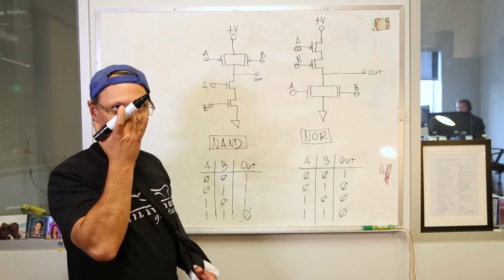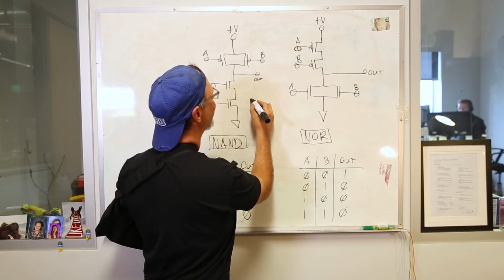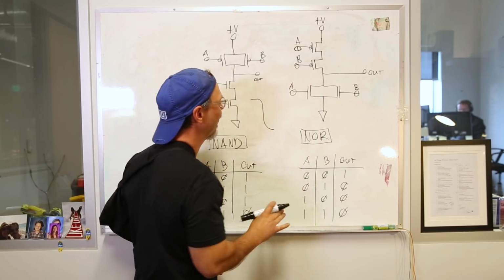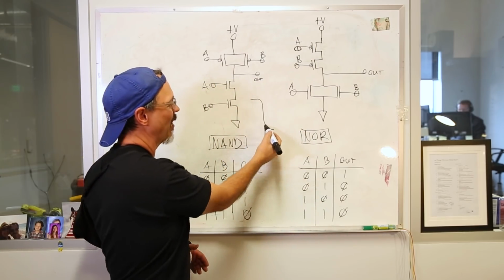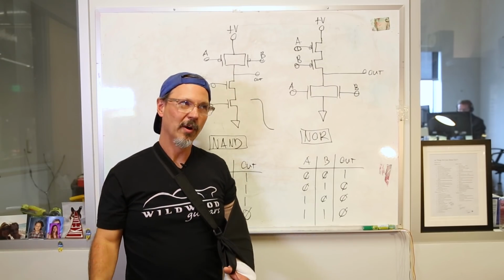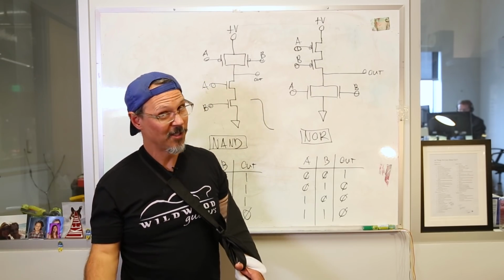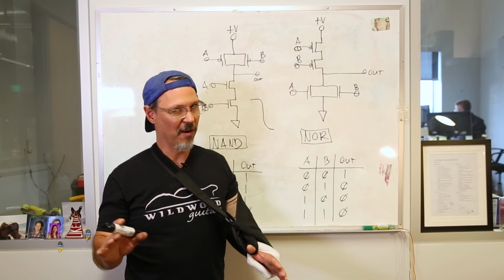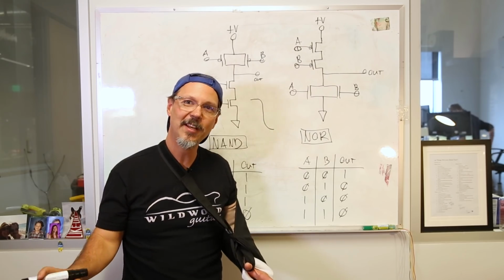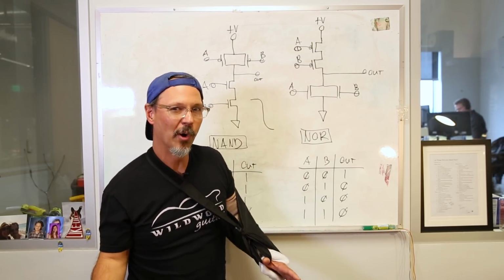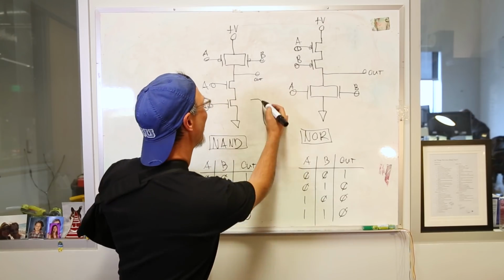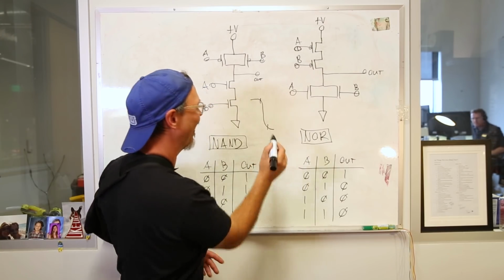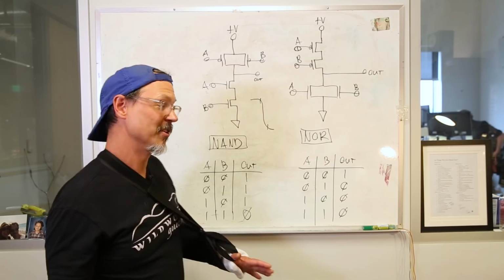And in fact, if you think about it, that little switching time, and I draw it this way because, look, all parts live in the real world. Ultimately, every single part, every active part, everything you've ever seen that's electronic is an analog part. But it's only analog from about there to there. And that's where all the trouble happens for digital circuits.